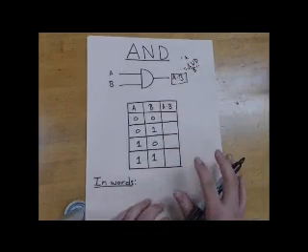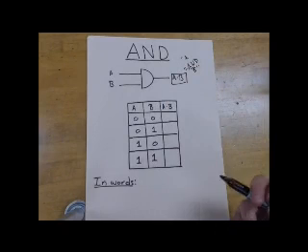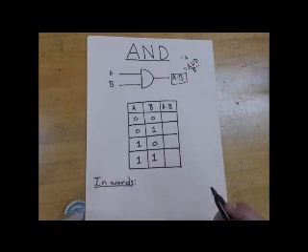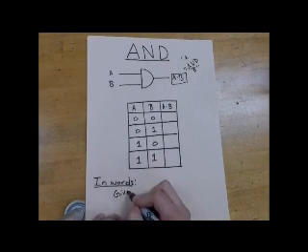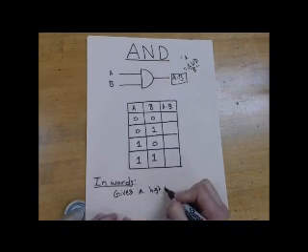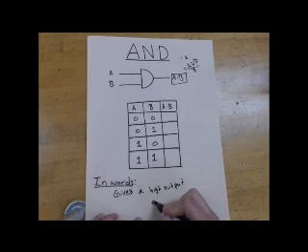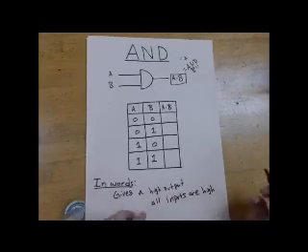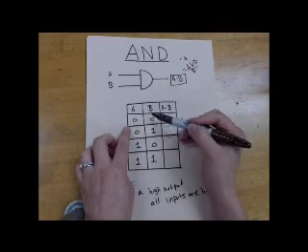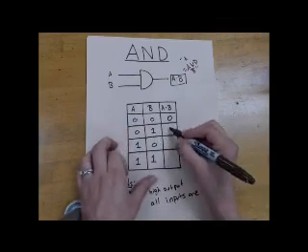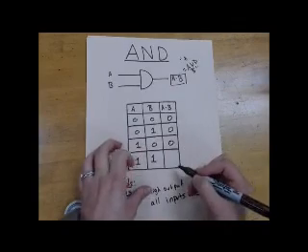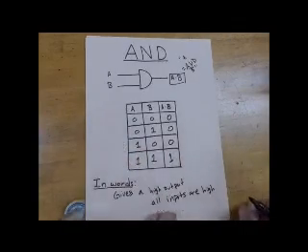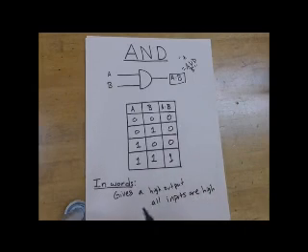And so these can get broken down into what are known as Boolean truth tables, and you should be able to also talk about these in words as well. So what does an AND gate do? An AND gate, in words, gives a high output only if all inputs are high. So what does that look like as far as this truth table goes? If we have 2 low inputs, low, low, we're going to have a low, and a low and a high, still a low, and 2 high inputs are going to give a high output. So basically an AND gate, once again, will only give a high output if all of the inputs are high.